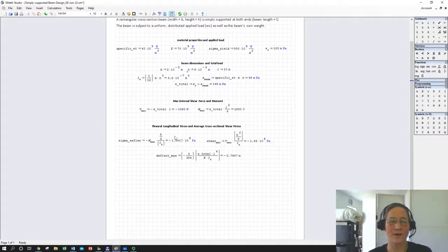Put that properly. So let's see if these numbers are more reasonable. This is still pretty high. This much deflection could be beyond the elastic range. Remember, our expressions for deflection were derived for small deflections, small angles. So this might have yielded, and it could be well beyond what would be allowable anyway. That's 3/4 of a meter. I don't think that we would want that much deflection.